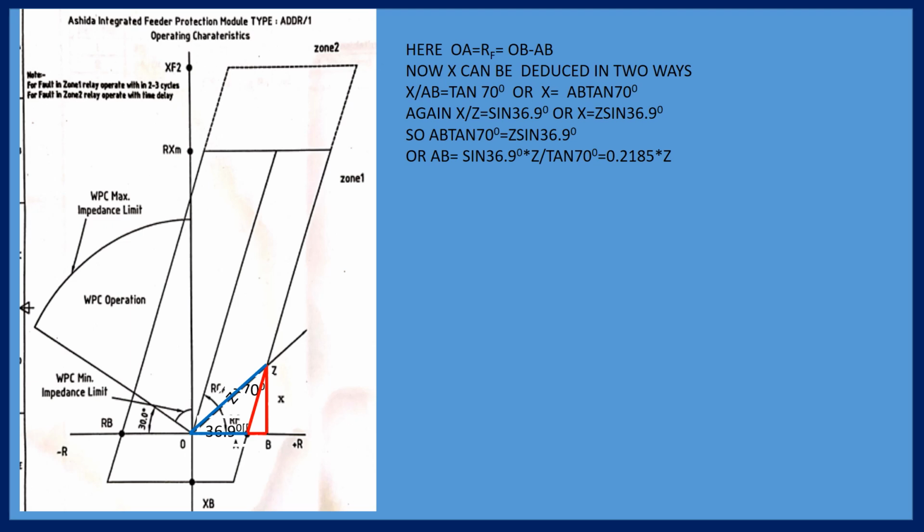Which we have checked in the DC testing, S1 S2, actually which you connect in the incoming phase where the current is coming and going to the power transformer, there the polarity will be the same, S1 and S2. But when the current is reversed in the other phase, it will be reversed.